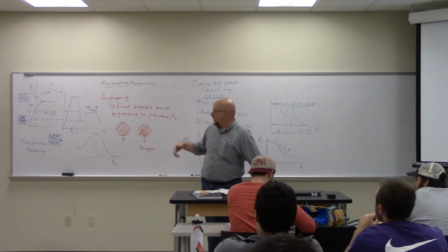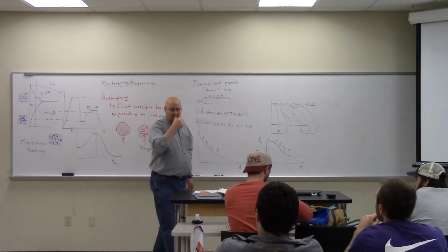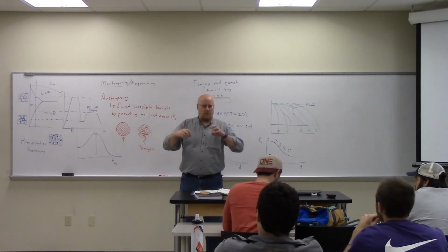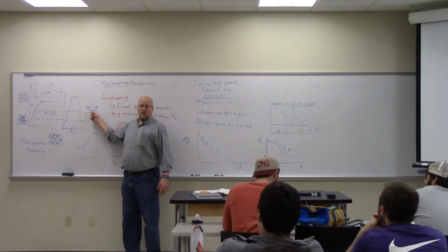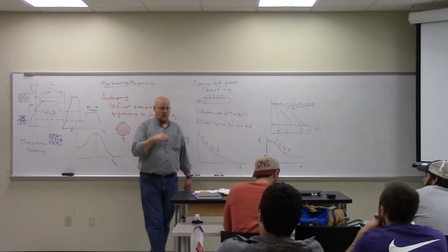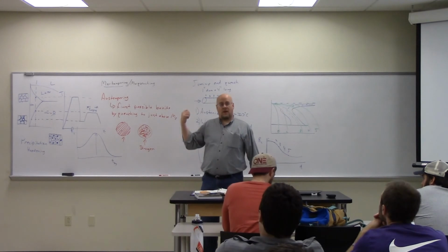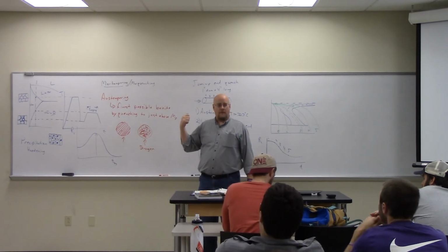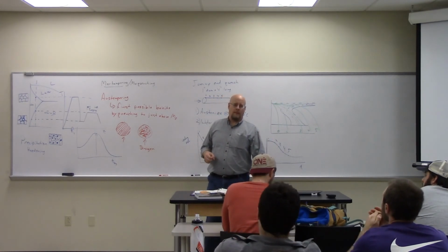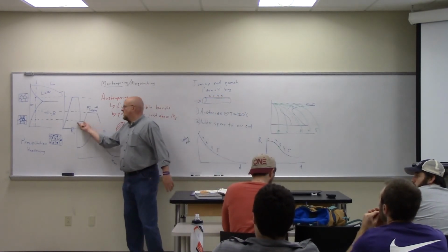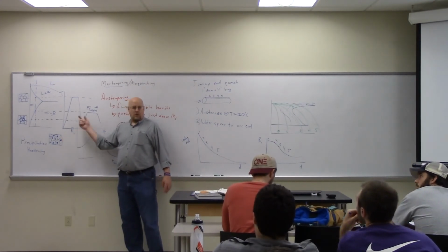Now, the other thing you can do, and I didn't mention it here, is cold work it in between. If I actually deform it a little bit, so I somehow beat on it or shot peen it or just somehow make some deformation, then when I raise it back up, the location where I have deformed it, where I've piled up dislocations in the microstructure, is where the beta will likely begin to form. The deformation will serve as a nucleation site for subsequent beta formation. So there are other things I can do in this time frame to accentuate the distribution of beta particles that I want.